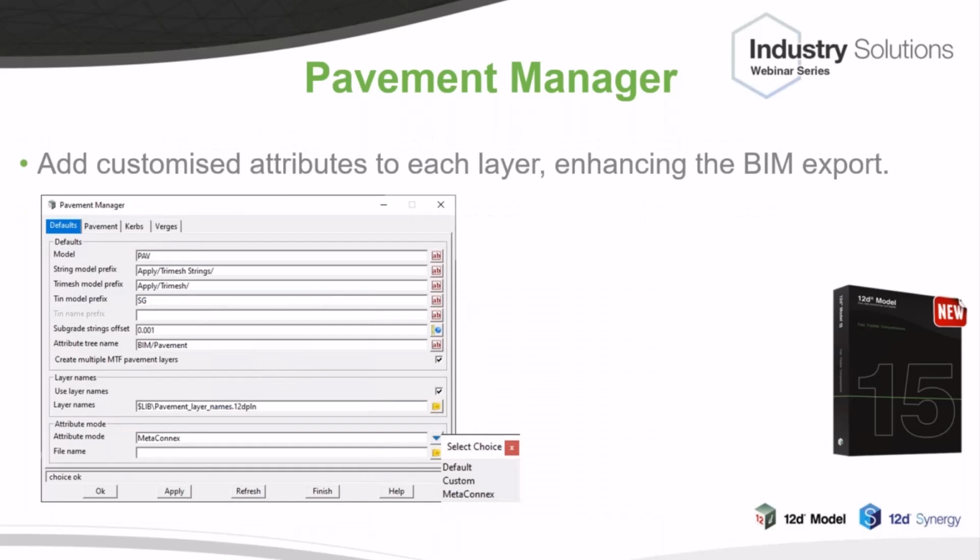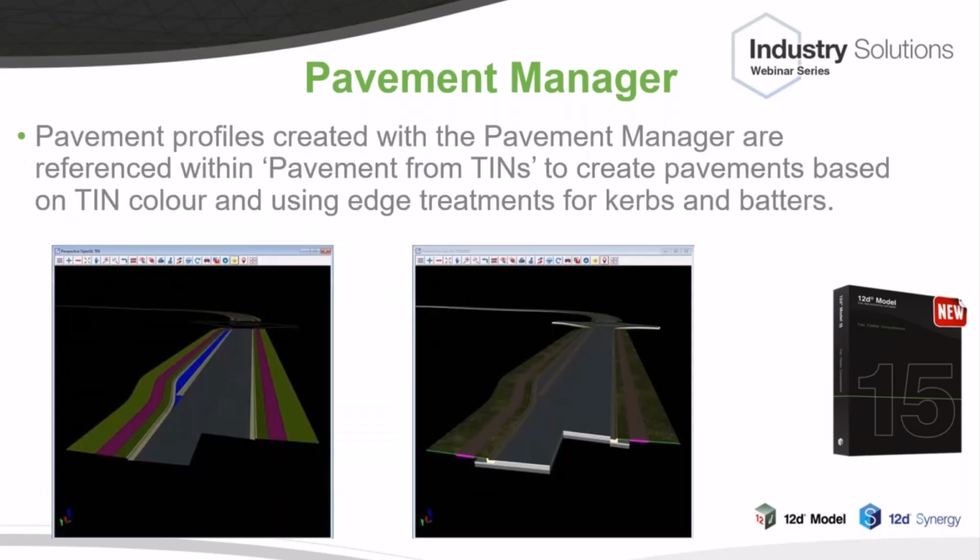One thing also is that you can add customized attributes to each layer, enhancing all that data for going out to a BIM export. You can use things like Meta Connects and set those attributes up. It also can work with pavements from TINs, to create the pavements based on TIN color, which is a very easy way of doing it when you've got complicated pavements, with little areas that it's working in. And so you can use the TIN color and edge treatments for the curves and so on.